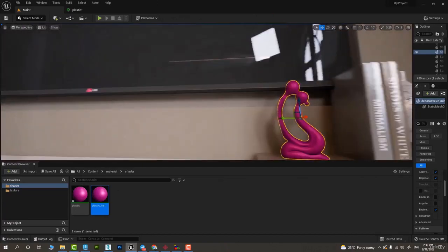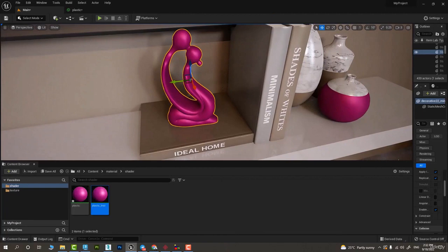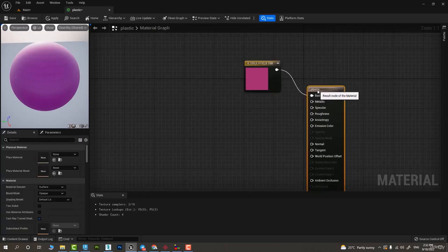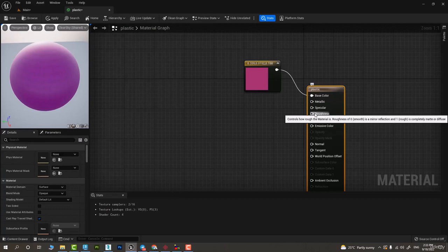And in terms of color, if we choose black for our roughness, it means that that object would resemble a mirror and we can just see ourselves in that object. It's very reflective. On the contrary, if we put white in terms of color for roughness, it means that that object is not that reflective at all, and it's like concrete or parquet floors. When we look at them, we cannot see ourselves.